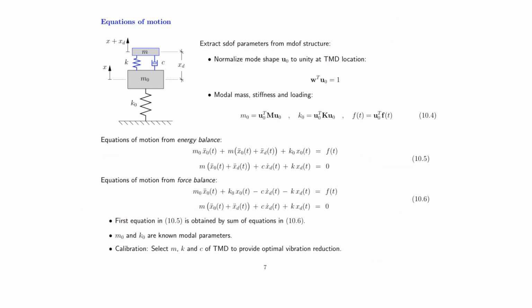And these two equations are given here. So if you go one slide back, you will recognize this one coming from x0 dot. And what was inside here should be equal to 0. The external loading is then moved to the right hand side of the equation, whereby the left hand side only contains our 2 degrees of freedom, x0 and xd. The second equation here comes from the other parenthesis we have here, that contains a common factor xd dot.